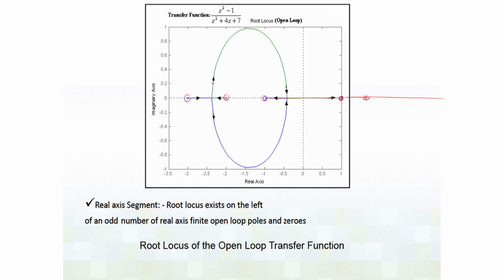On this test point, what is the phase contribution of the zeros and the poles? Let us look at the first zero. If I join these 2 points, this zero is directly hitting here, and that would mean that we are going to have basically 0 phase angle here.